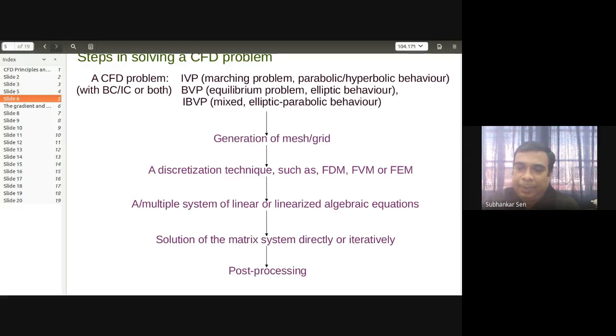It may be Gauss elimination, Jacobi, Gauss-Seidel, or Gauss-Jordan. These are matrix equation solvers. And when we say I am using a CFD solver, we mean the discretization method: we have the differential equation, and we convert it into algebraic equations. That is the function of a solver.